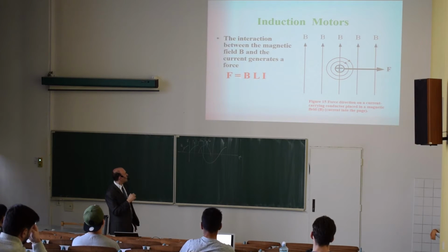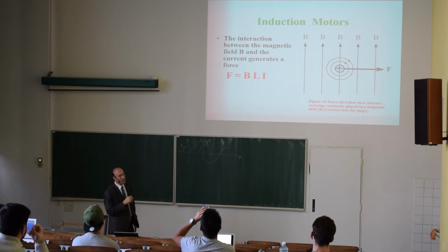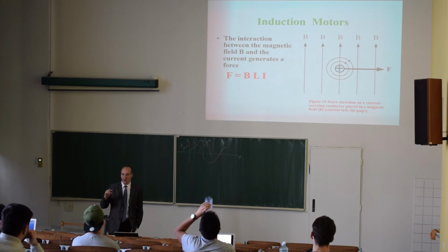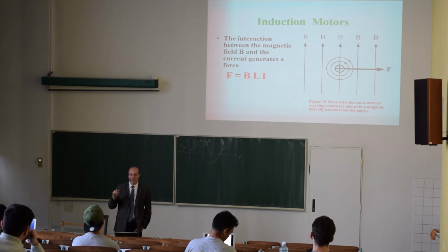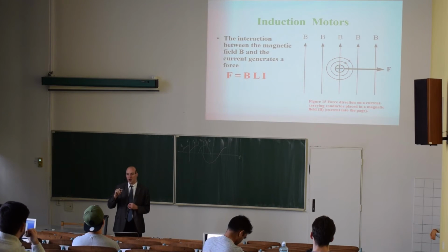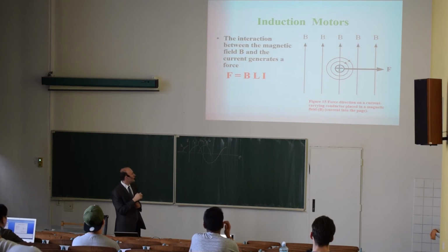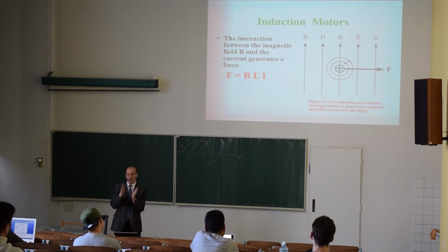And also, this will be limited by the air gap. When we did calculations of the magnetic circuit, we saw that basically the magnetic resistance of the magnetic circuit is given by the air gap size. So you can increase the torque by making the air gap smaller.